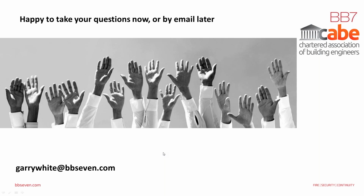Excellent. Okay, thank you. Now, a technical question here from Paul, who's asked, can we run 150mm full fill cavity insulation, for example Cavity Therm, between two masonry walls with a 150mm cavity to meet the window without the need for a proprietary cavity closer around the opening? Just to clarify, are we talking about the exclusion here, where we've got two masonry leaves 75mm thick?